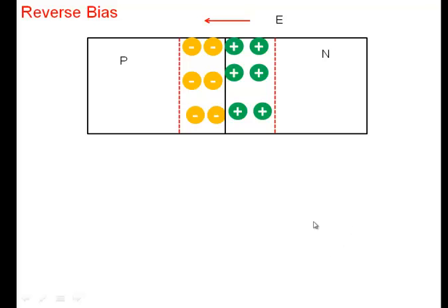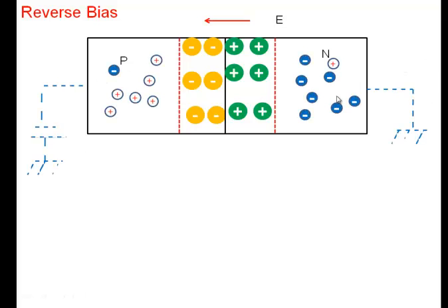All right, let's come back to reverse bias. What happens in reverse bias? For reverse bias, we'll take P and make it more negative as compared to N. That's what we're going to do. Now, this is reverse bias here. As I said, this voltage again will propagate to the junction. And now, what will it do to the electric field?